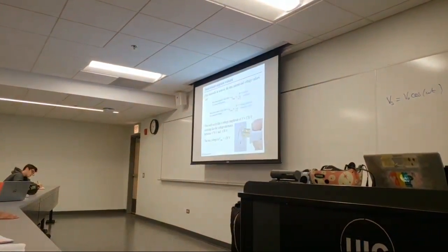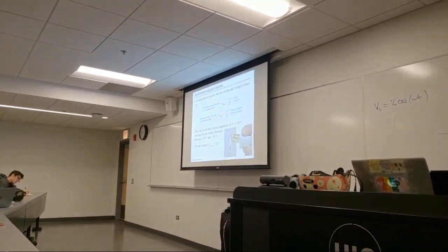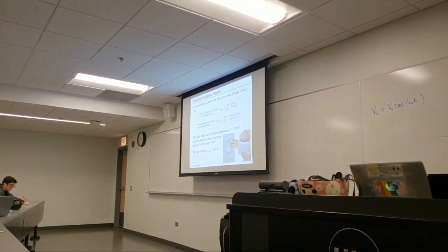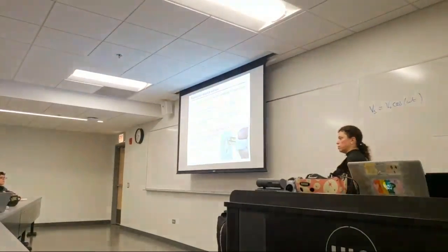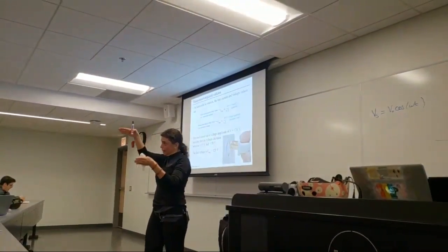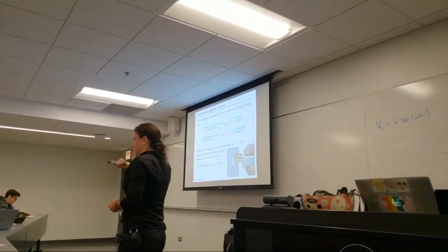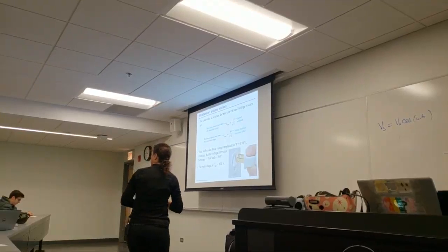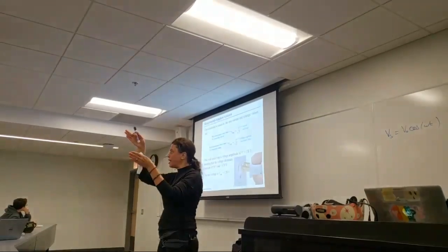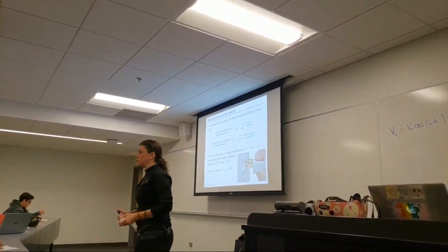We're going to describe the voltages across, or the currents across, different elements of our circuit as vectors that we call phasors. The characteristic of these phasors is that their length doesn't change. They're just rotating on this phasor plane. If we want to know the instantaneous solution of what's going on in each one of these elements, like the voltages, we just project these vectors onto the x or real axis, and we get the solution. All right?